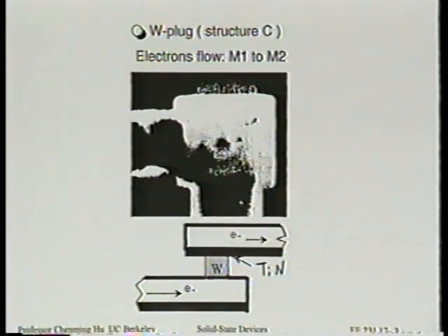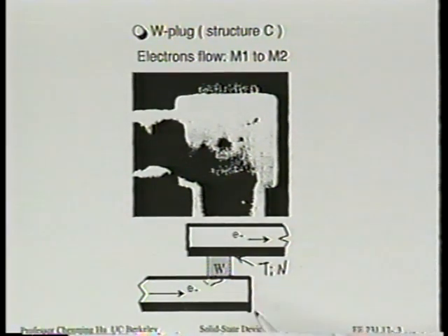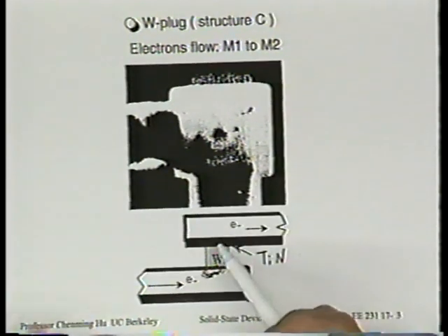And this material is a conductor, but has very low mobility, similar to tungsten, so it does not suffer from electromigration very much. In this case, even if some voids start to form here, aluminum moves away from the titanium nitride interface, current can still flow from the tungsten plugs through the titanium nitride. You see what I'm saying? Yes, flowing to aluminum. Or in this case, I'm showing the electrons flowing from metal 1 to metal 2. I'm sorry. So we actually expect a void to form here.